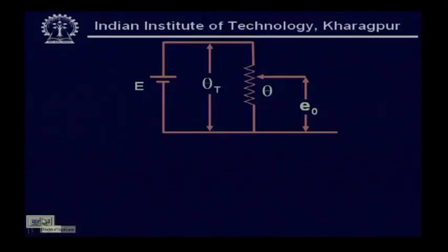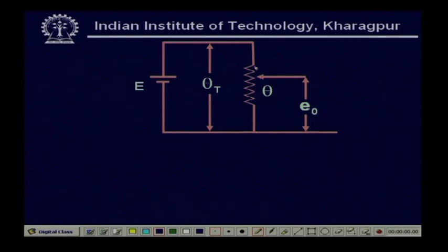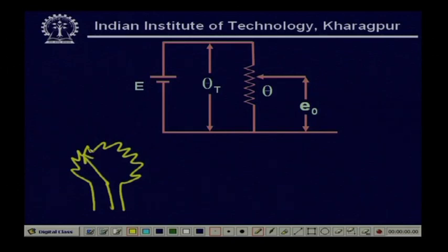These are basically potentiometers. A potentiometer is a 3 terminal device. This is our potentiometer. I have a supply excitation voltage and a total angular rotation of the potentiometer. Physically, it looks like this. I have a wiper, or jockey in the case of a rheostat, but the principle is the same, both are zero order instruments.